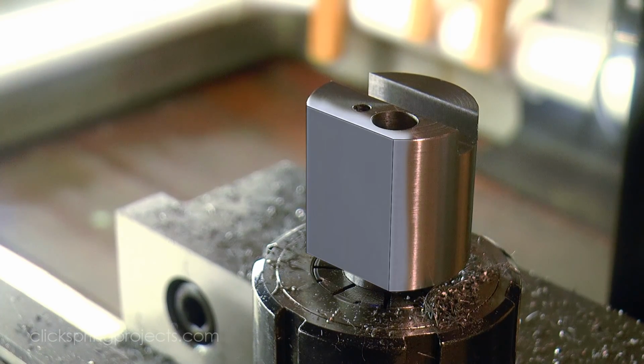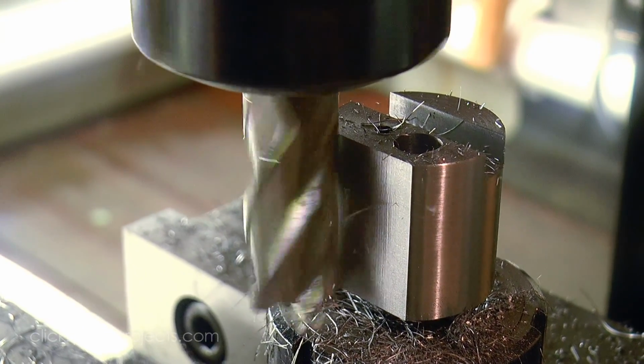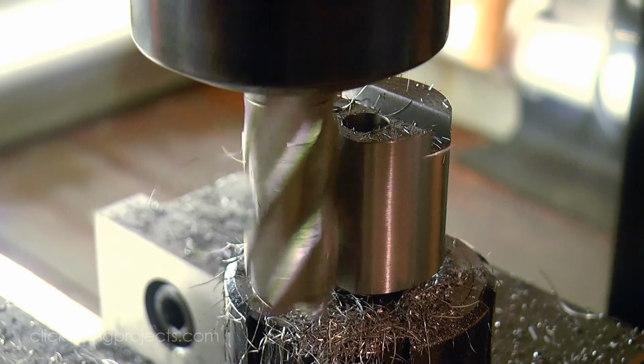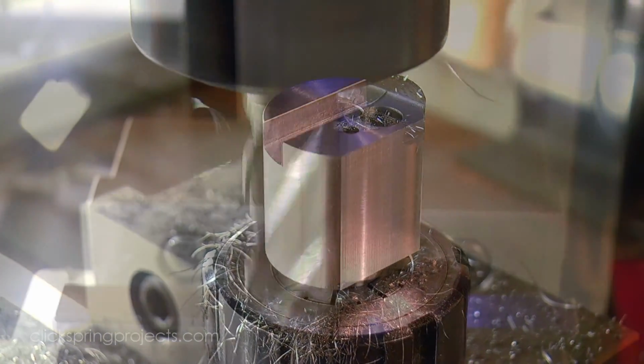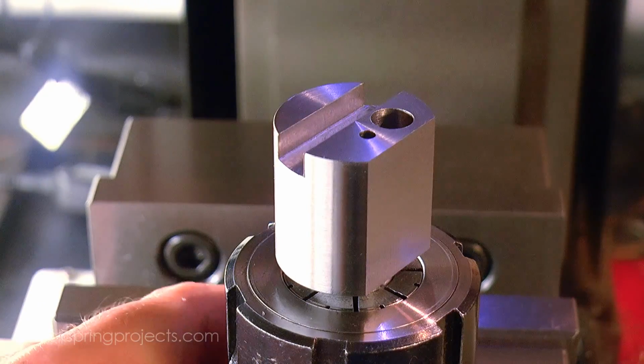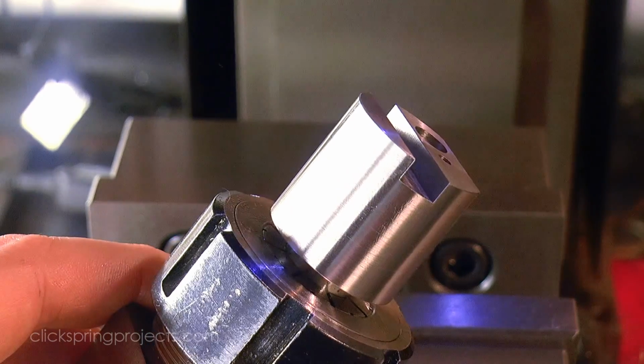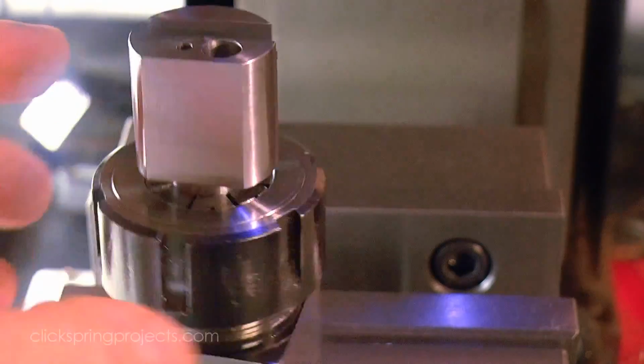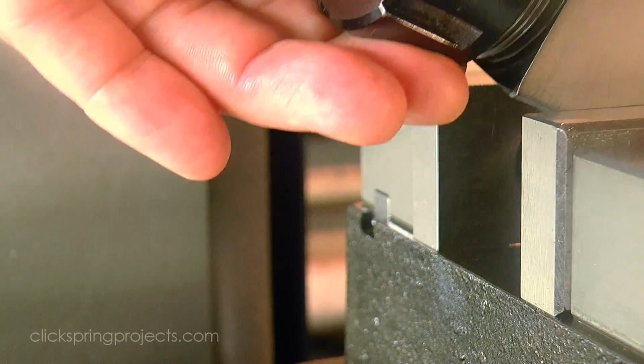It's also a fixture to hold onto the multi-tooth cutters for the milling operation that reveals each cutter tooth. This large flat serves to both balance the tool and give us clean access to the section that we'd like to mill away. And then by removing a small section at the back, we get a means of both aligning and gripping the whole structure in the vise, as you'll see in the next video.